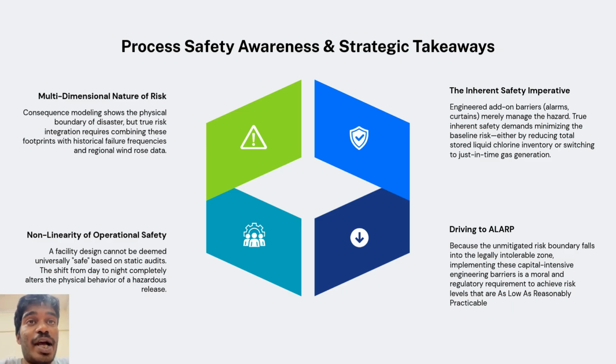Ultimately, this challenge highlights a vital mindset shift for us as young engineers. Consequence modeling in effect shows us the physical boundaries of a disaster, but true process safety requires integrating those footprints with failure frequencies and regional wind data inside risk curves. We discovered that safety is highly non-linear. A simple shift in the clock from day to night transforms a manageable release into an absolute catastrophe.